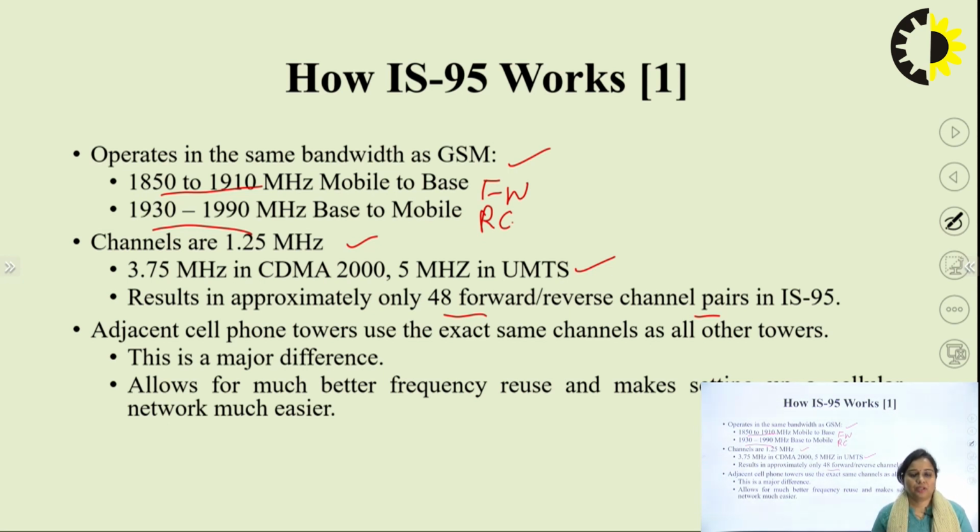In adjacent channel and co-channel, there is a formula associated with this, that is N equals i square plus j square plus ij. What will this decide? This will decide the cluster size, and it will also decide the two co-channel cells which are using a common set of frequency range. So, that is the case of adjacent channel or co-channel cells.